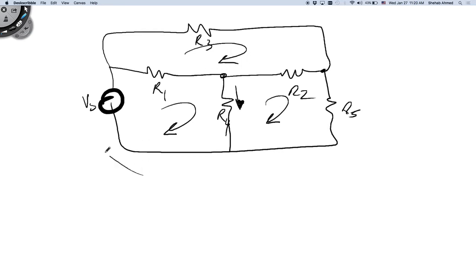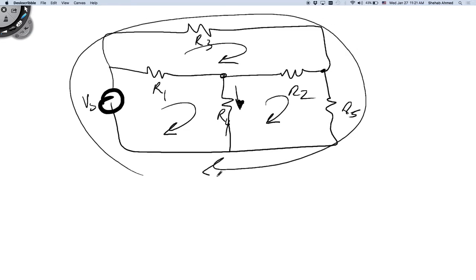and you can do another one here as well. So all of these 4 loops will give you different equations that contain the value of voltage drops across all of these values of resistors, right? And if your number of equations and number of unknowns are equal, then it's a linear system and you should be able to solve it. That's one way to do it. And we will do it that way in a little bit. So we will build up to that.